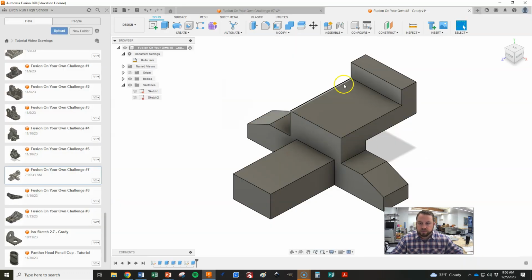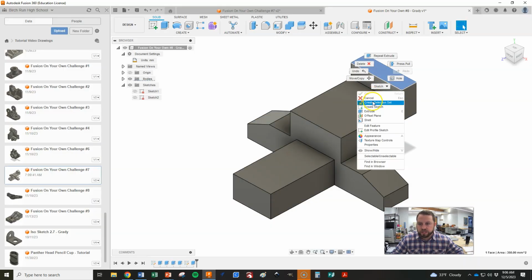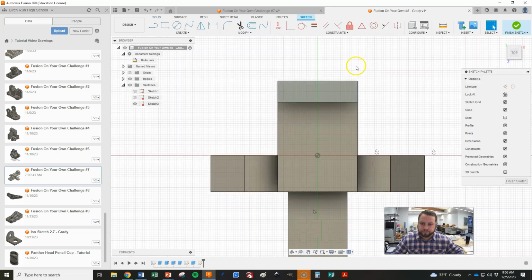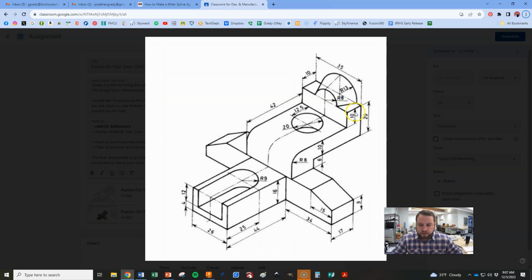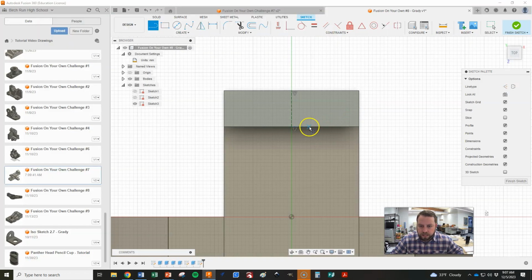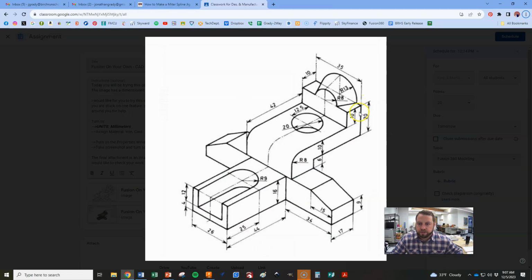Okay, so we're going to create a sketch up here, and we want that right at the midpoint. Construction line, midpoint to midpoint. Alright. And then we need to continue with our line tool, and we're going to draw it somewhere over here, and then we'll add some dimensions.